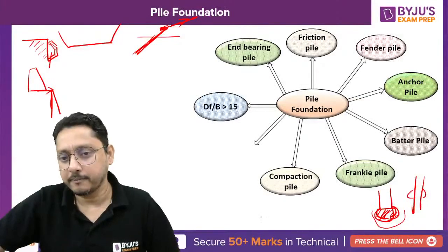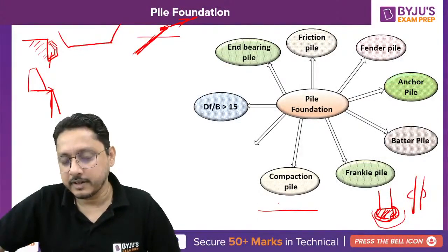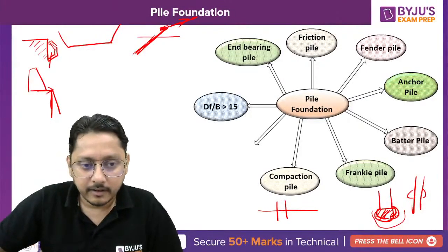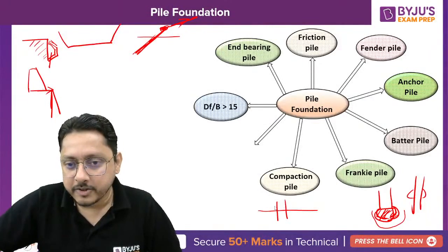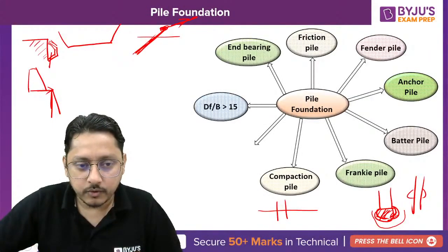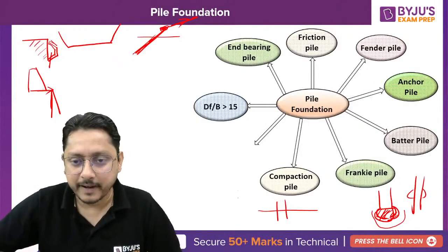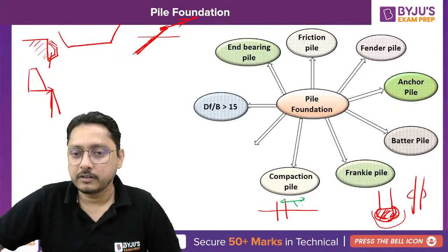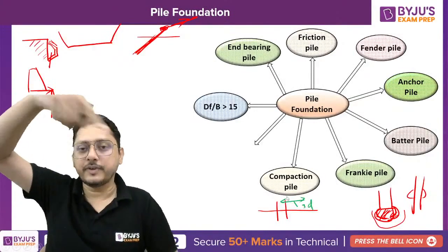And you also know that generally for loose sand, if you are providing the pile, it can influence the compaction from its center. If you consider it from the center of the pile, at least thrice the diameter, it can influence that much area for the compaction.